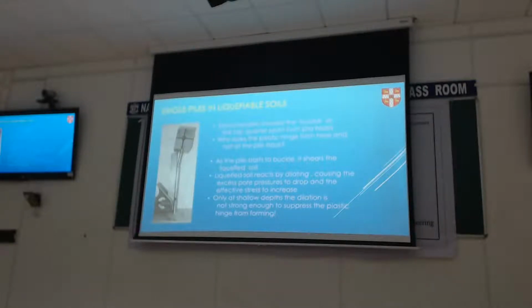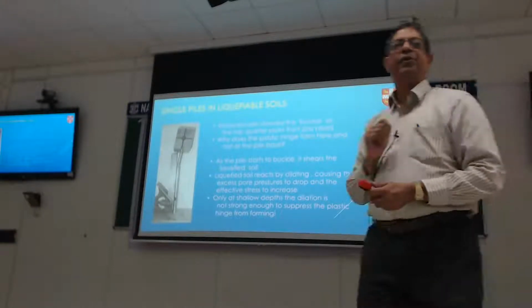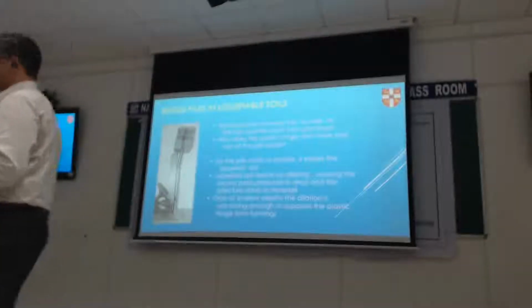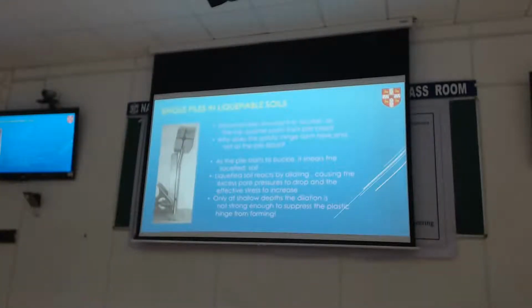So you will form a plastic hinge according to the rules of plasticity in the pile. However, where that hinge forms is dictated by the liquefied soil. So the lesson we learned is that liquefied soil is not going to behave like a liquid. It is a shear dilating, shear hardening material when you force it to shear.